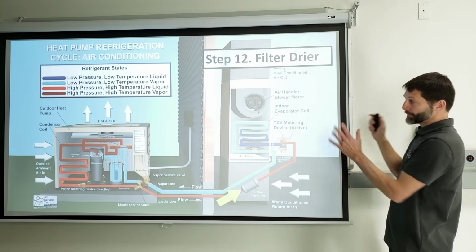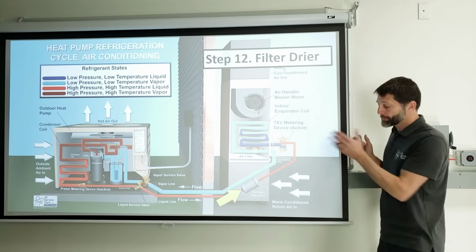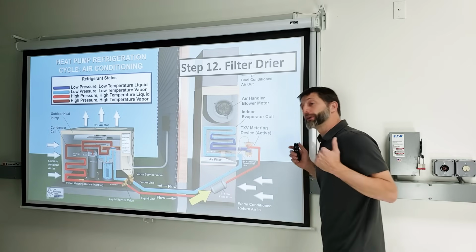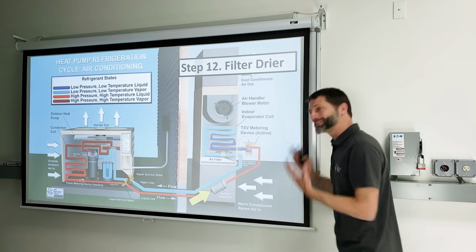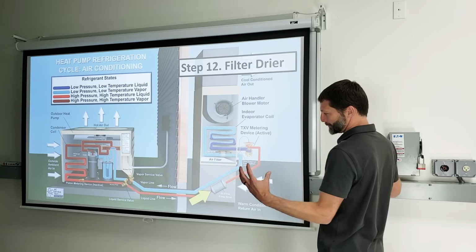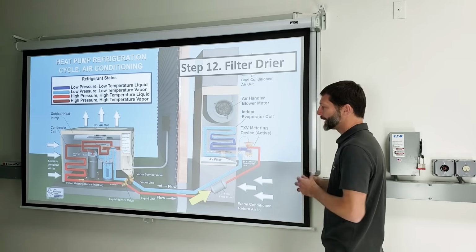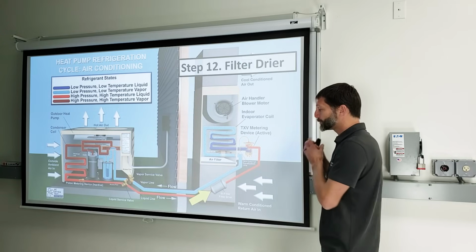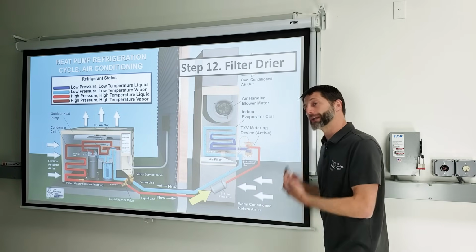But in this case, you have a comfort cooling, air conditioning, or heat pump system, so it's likely POE. And that is very hygroscopic. That means, that's a fancy word once again, it means that it really grabs the water. And the problem with this is that POE oil mixed with water is going to create alcohol and acids.